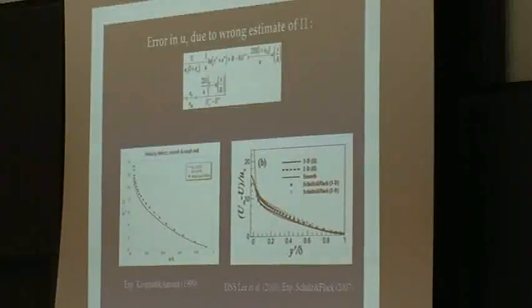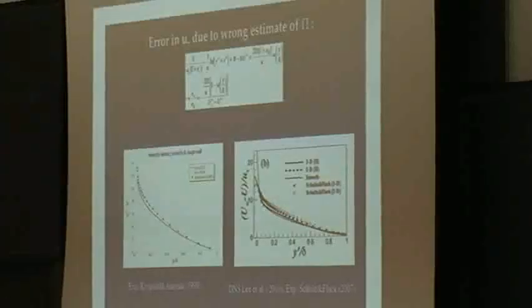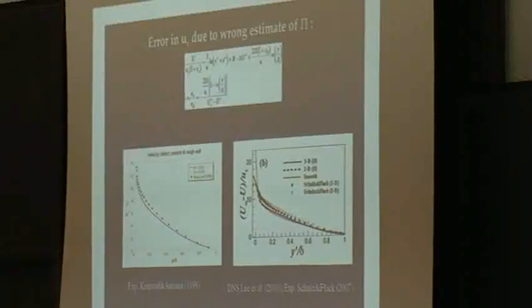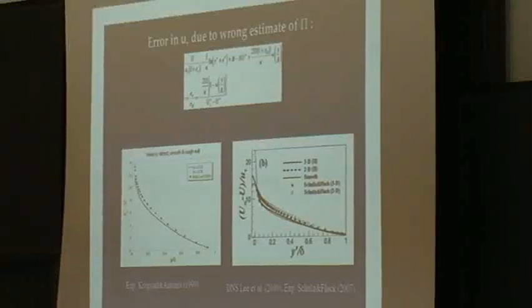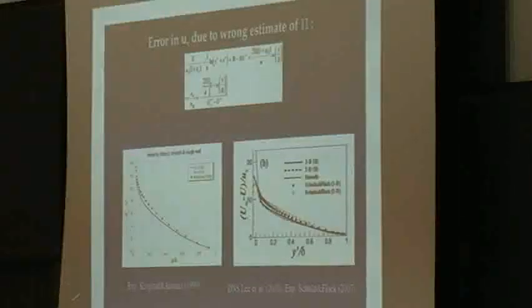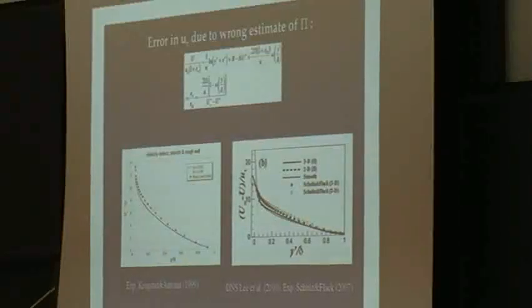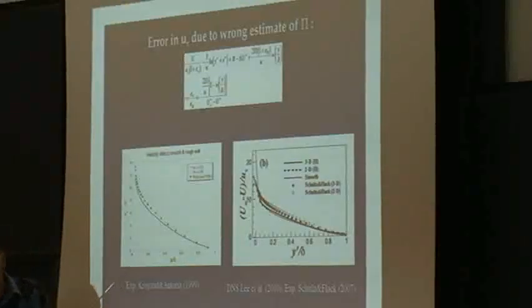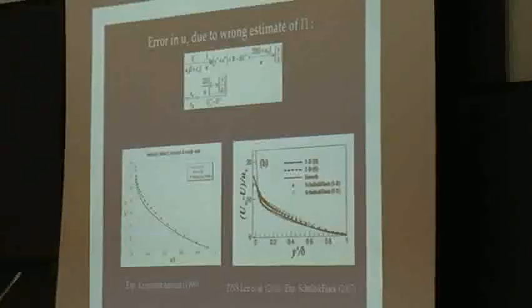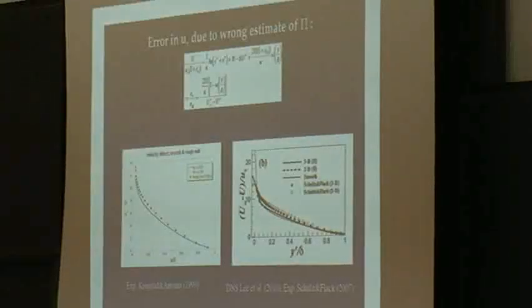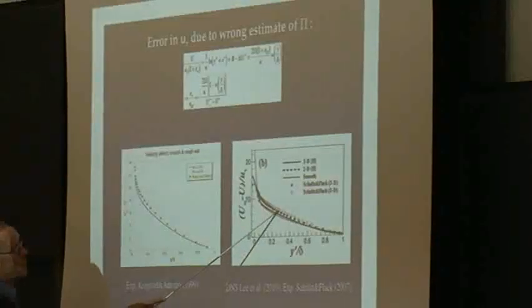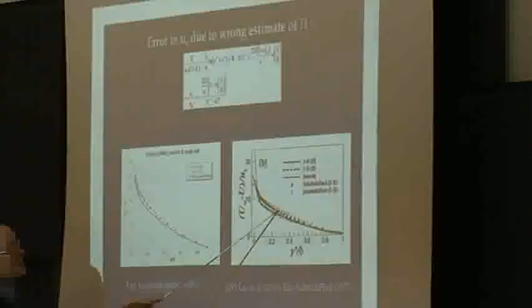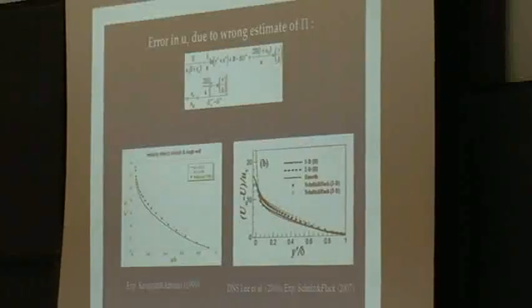that you get from your curve. When we presented this, a lot of people seemed to object to our measurements, and it gave me a lot of sleepless nights, of course, because of all the criticism. But then people started to repeat measurements which had similar geometries, and some of them, like the very recent measurements of Schulz and Flack from America, seem to support our finding that at least there is a shift when you go from a smooth wall to a three-dimensional roughness to a two-dimensional roughness.